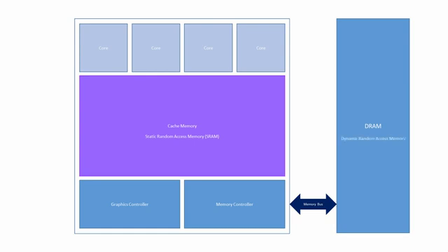The memory cells in DRAM, that is dynamic RAM, on the other hand, are based on capacitors. DRAM cells leak their charge very quickly and therefore need regular refreshing. But DRAM cells are smaller and cheaper to manufacture.